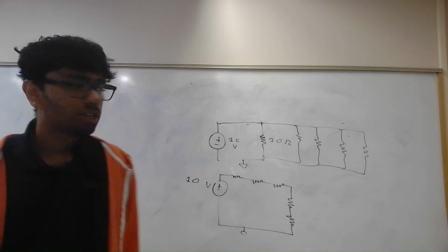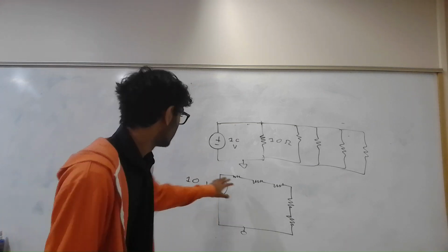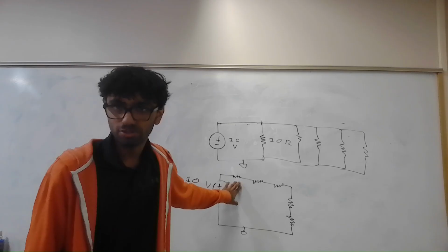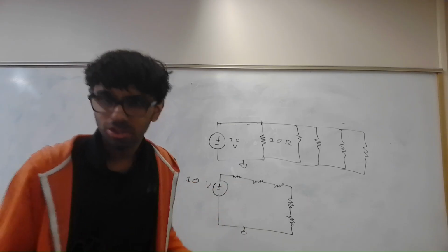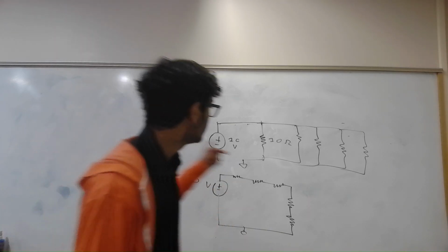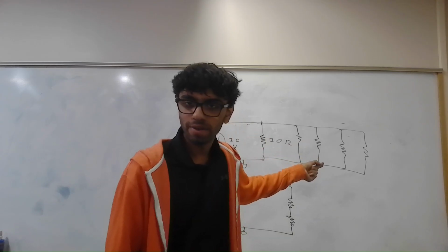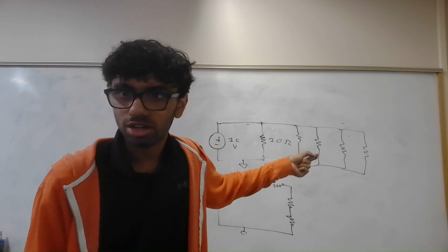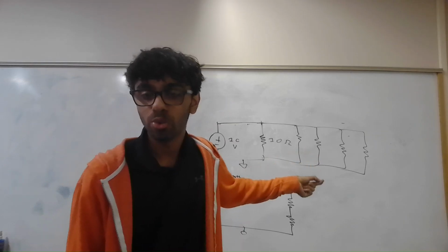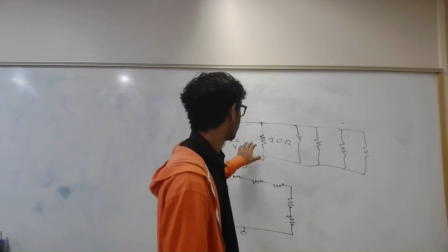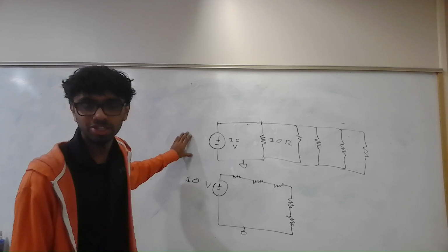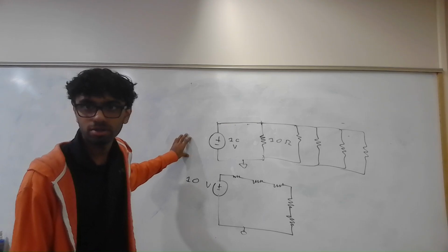Okay. So here, each resistor drops only a portion of the voltage, meaning that there's a lesser current flowing through them. Here, each resistor drops 10 volts, right? And so there's a greater current flowing through them, total. Okay? And so as it turns out, this is the configuration that requires the most power.